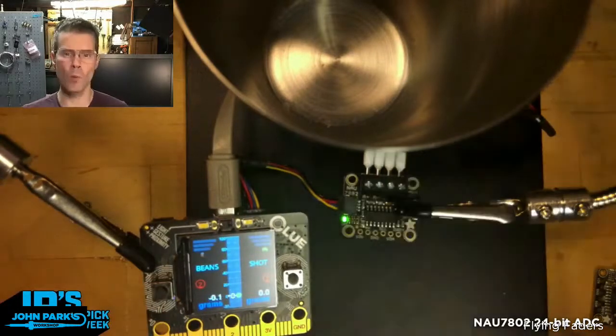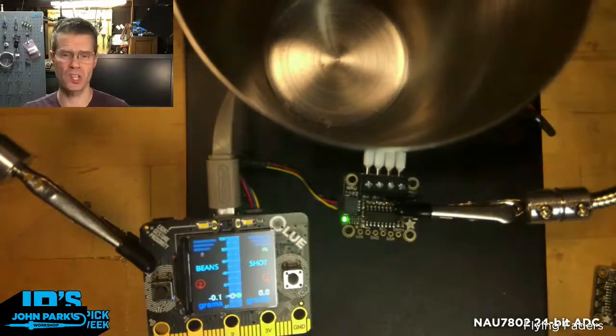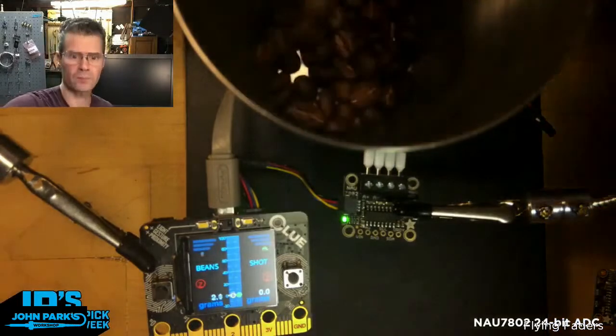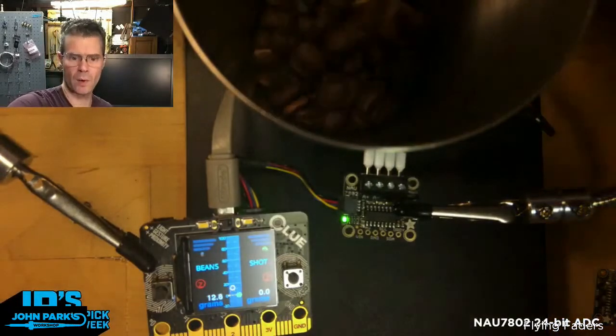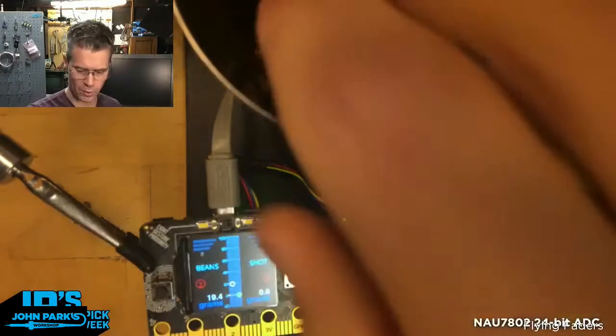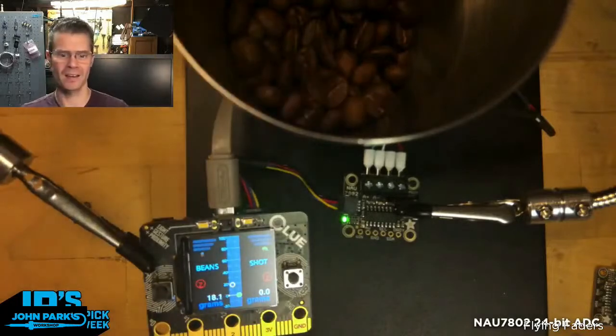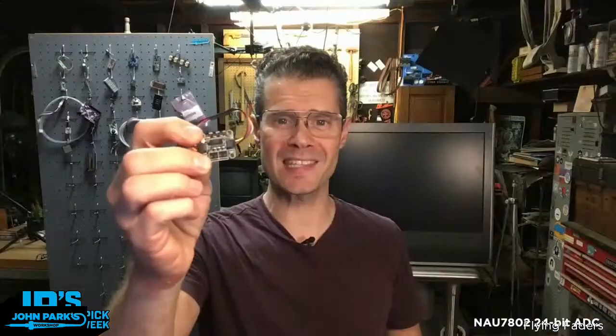It's going to remove the weight that it sees on there from the starting point. So now we're at 0. I'll start pouring these in, and you'll see that the weight is going up and up. 18. Oh, I went a little over. I'll pull some out of there. Okay, watch this. I'm going to put one bean in, and you can see it's a really precise measurement. That went up to 18.1 from 18. It is the NAU7802 24-bit ADC for measuring strain gauges and load cells.